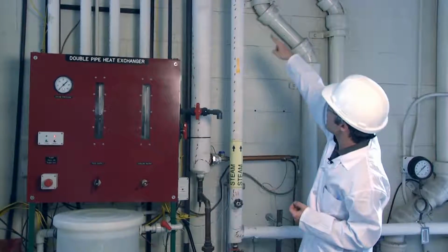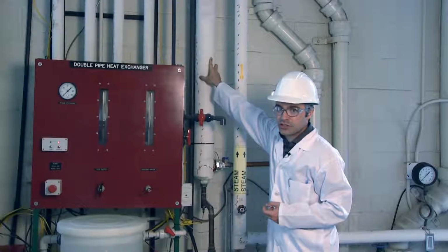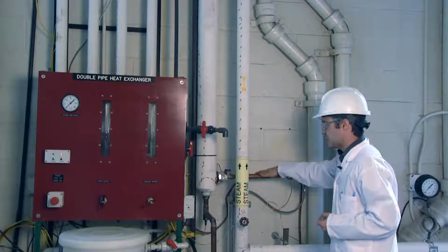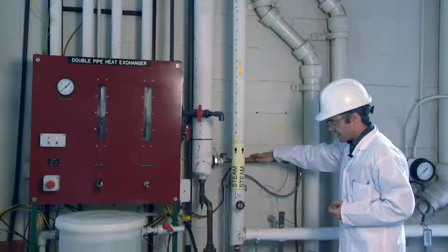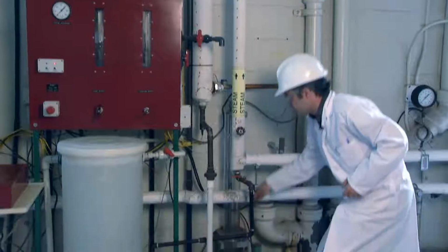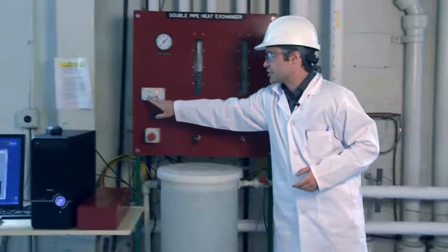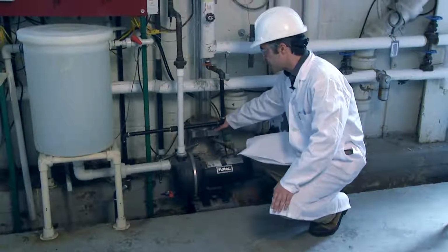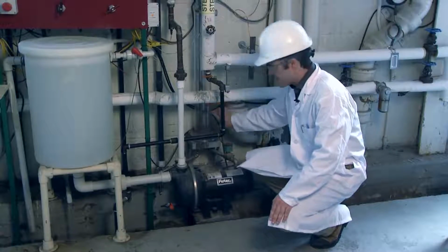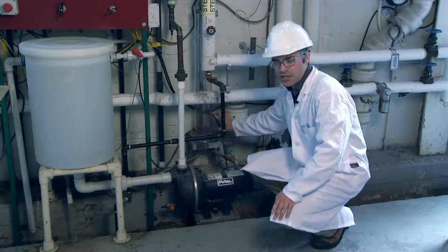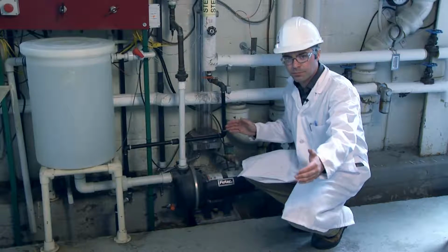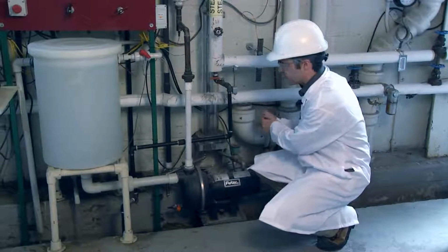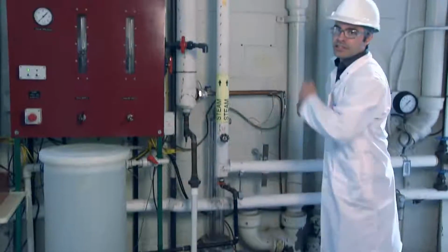The steam will travel up, interact with the circulating water here. The condensate will again move through a steam trap, come out of the pressurized area, will be condensed and then collected here. Once you begin the collection, this solenoid valve will engage and the condensed steam will begin to fill this reservoir. The amount of steam condensate that you collect over the course of your sample collection period, usually 15 minutes, will be how you determine how much energy is transferred from the steam into the circulating water.